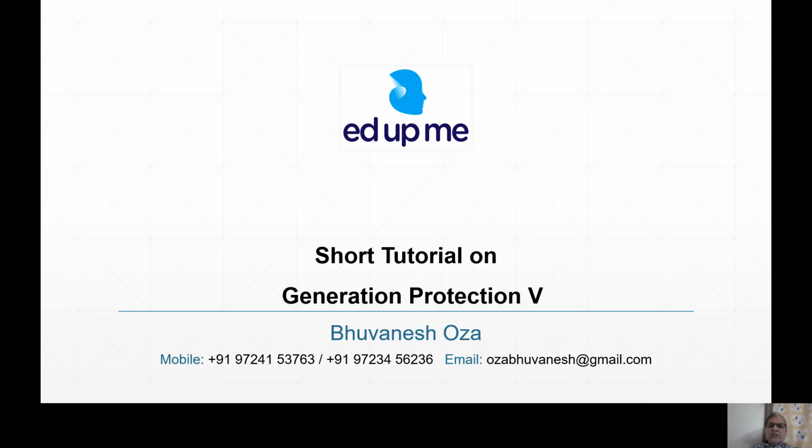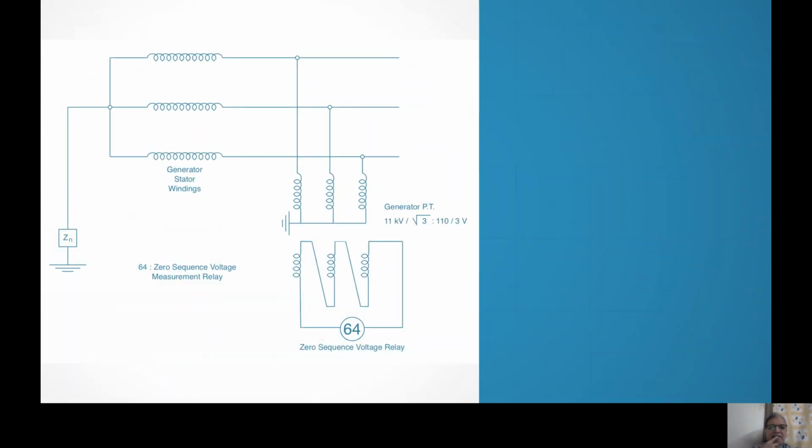And for large generators, we would want to reduce the earth fault current to a very low value, primary 2 amperes. So that would lead to no winding being protected for earth fault. So that cannot be used. That we have proved. So what can you do?